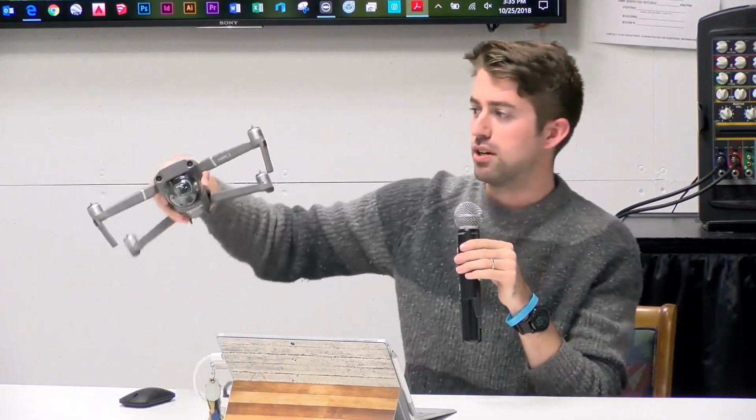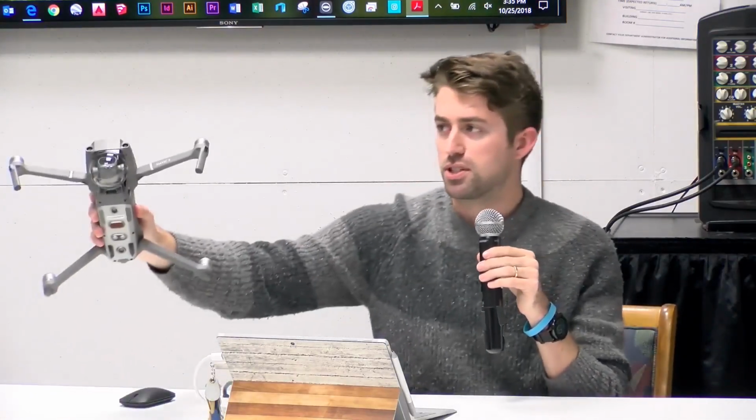What if you have a windy site? What are the parameters for that? These fly about 40 miles an hour tops, so in 40 mile an hour wind, you're going to be able to stay steady. The general rule of thumb is you fly on a clear, calm day. But with the wind, you'd be flying tilted like this, right? Yep, it'll tilt up, but the camera has a gimbal on it that adjusts, and it is always steady. So even if the drone's tilted like that, the camera's going to be flat level.